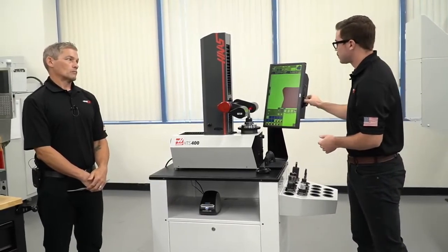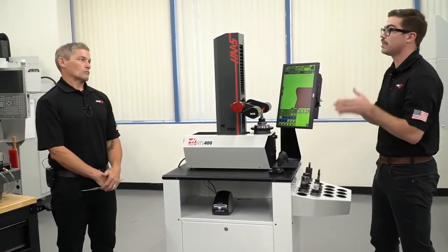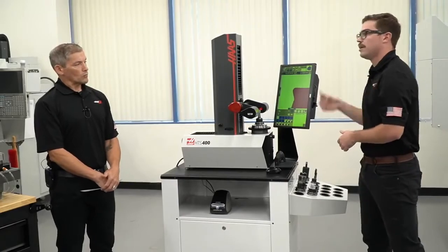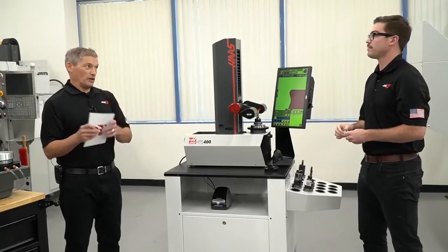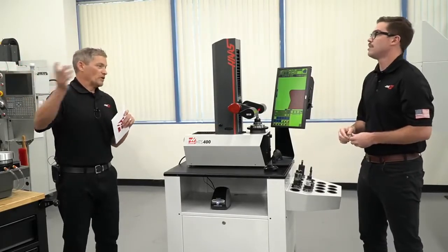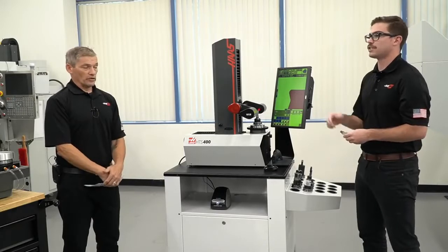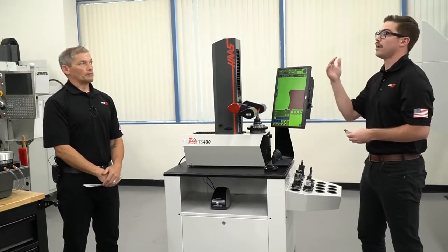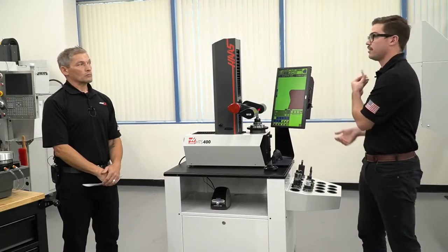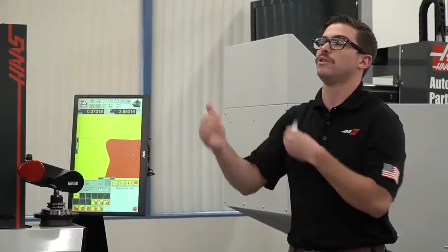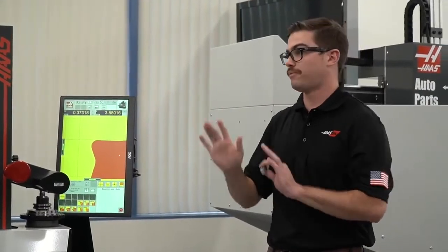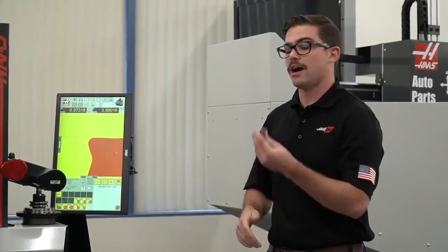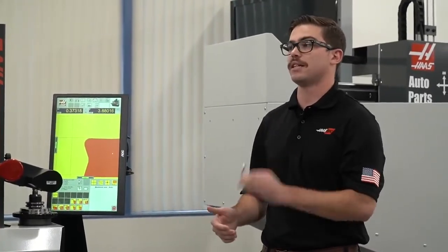Another thing you can do is take those offsets, because we created an entire tool list, and export them as an offset file onto a USB. Then you go over to your control, plug it in, upload that offset file, and it'll automatically update your tool geometries. Right, so you might load a whole new job, 10 tools or something, and update all of that at once. Correct. Even if you have 50 tools and I only want to update the geometry on 3 of those, I still create this one offset file. When I load it, it's only going to update those 3 tools and leave the remaining 47 totally fine.